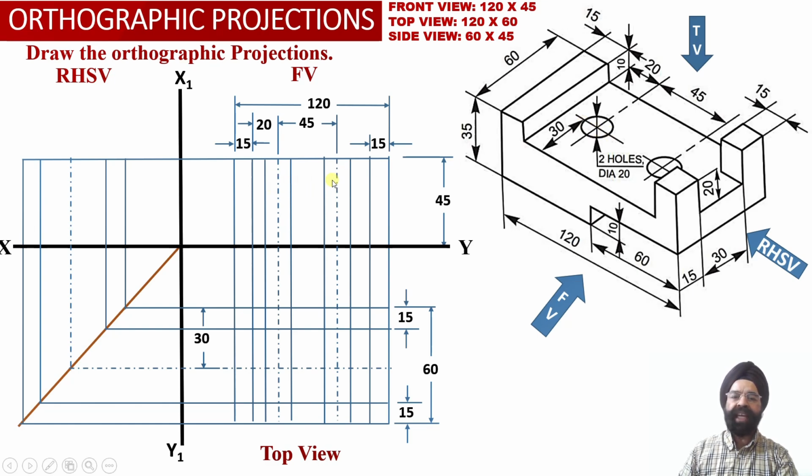So from these center lines which we had obtained in the front view projection and in the top view projection, now we are going to have an offset of 10 millimeter on either side of the center line, so that the diameter of hole number 1, which is equal to 20 millimeter, can be obtained in the front view projections, and the diameter of the hole as 20 millimeter has been obtained in the top view projections as well. Similarly, corresponding to hole number 2, so this was our center line.